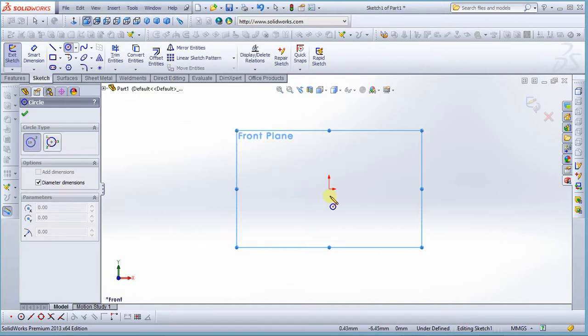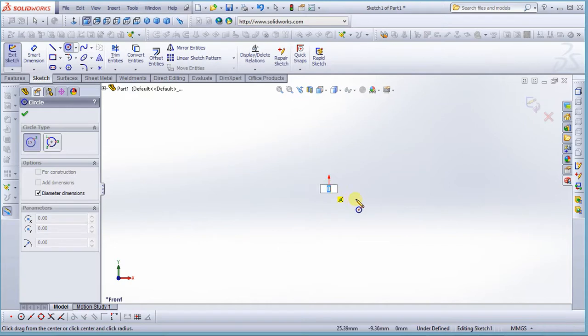That pencil shows that you want to draw. Anywhere you want to start, I want to start from the origin. I want to start a circle from the origin. I'll click on it and drag down. In this case, you see a small box which shows some figure there. That figure provides you with an option where you can directly put the dimension of your sketch.